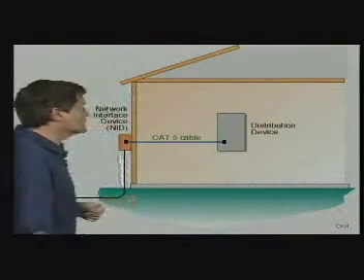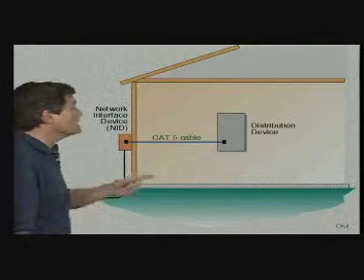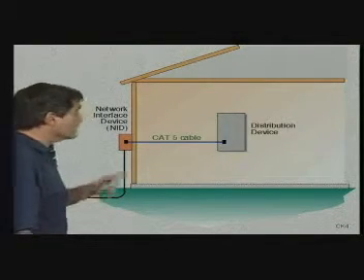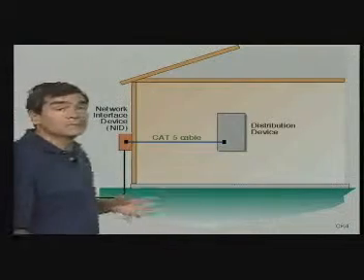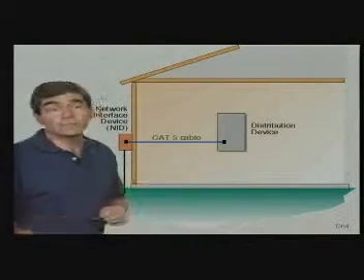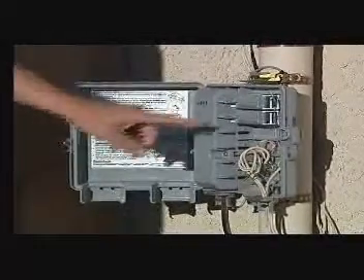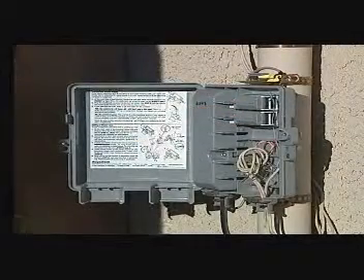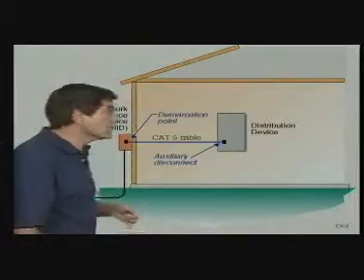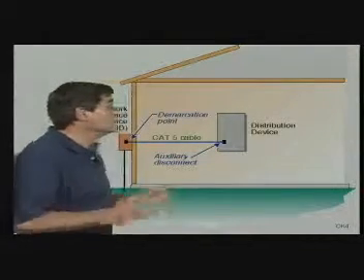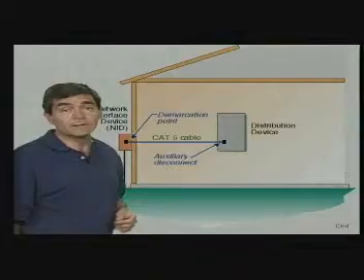Outside services are brought to the house and terminate in a network interface device, or an NID, a location or device that defines the termination point for outside networks like cable TV or telephone service. The NID contains a demarcation point where services can be disconnected from in-house wiring. There's also an auxiliary disconnect, where outside services can be disconnected at the distribution device.